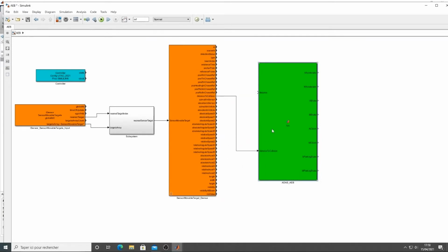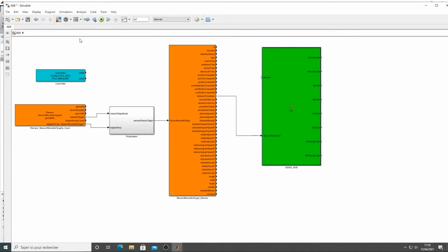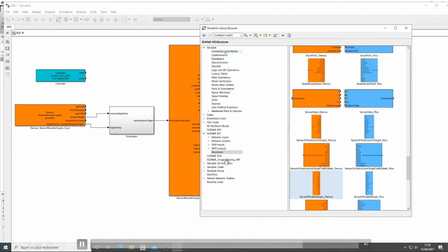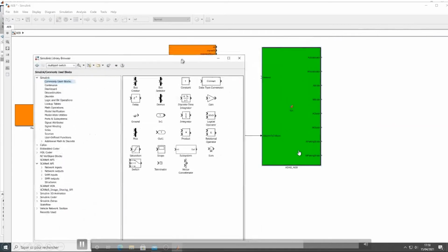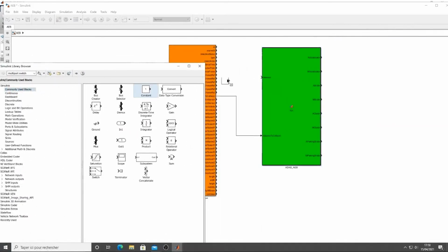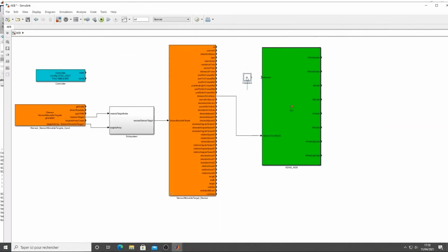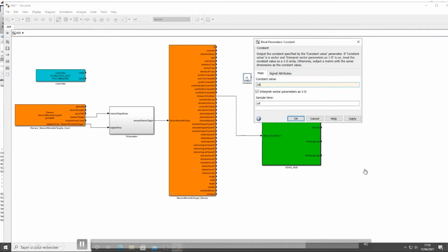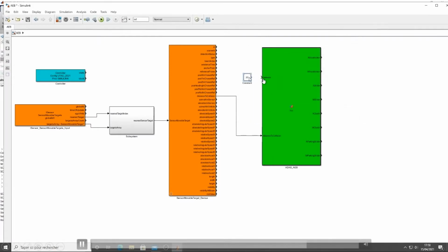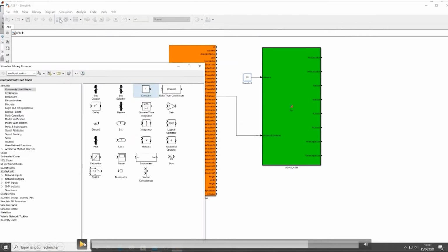What this block does, it's a very simple emergency braking system. It takes the distance to the closest object in front of the car, so in front of the sensor. And with the parameter on top that is called distance, when distance to the collision is lower than 20 meters here, because we have chosen a constant, then we will put a maximum of pressure onto the brakes.